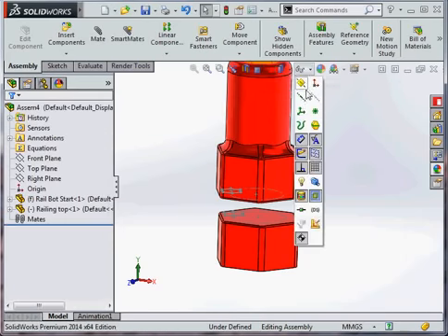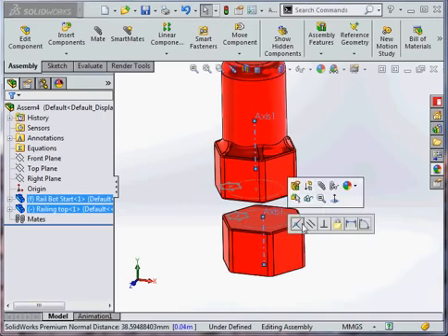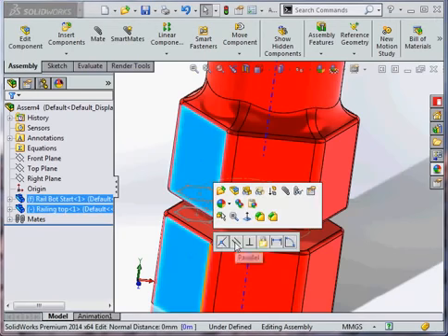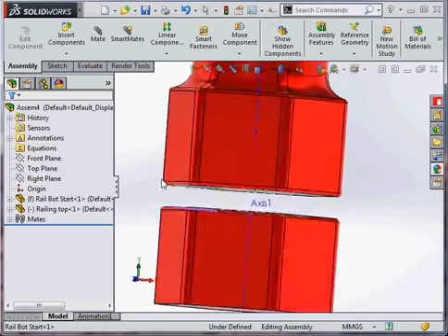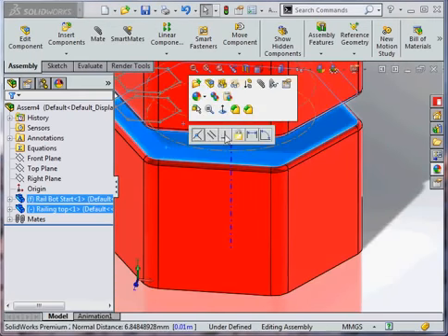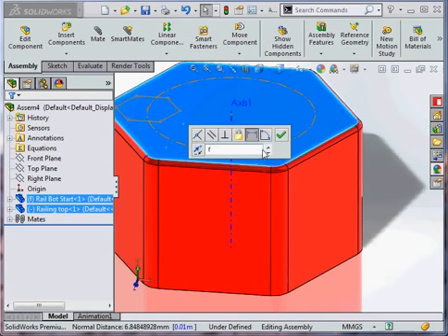Into my assembly. Then all that's required is just to position these together. I'm going to make their axes, and we're going to put some home positions. So I'm going to make these two faces parallel and give them the set distance for the little bar that goes between them. Okay, so this clearly is only my home position.